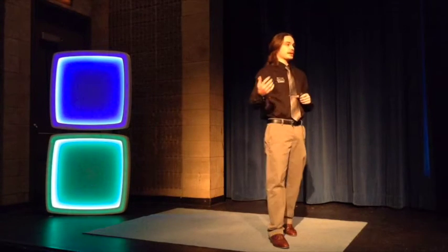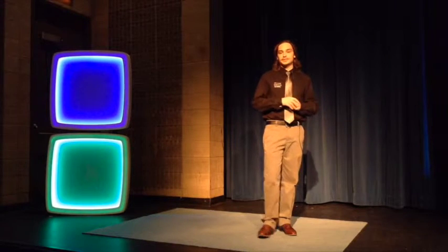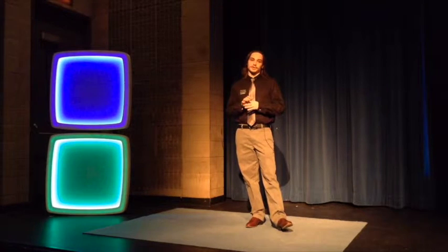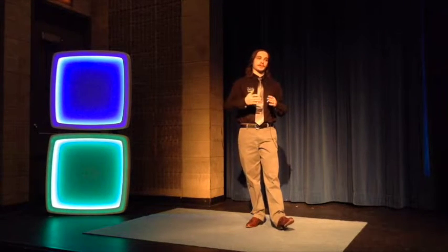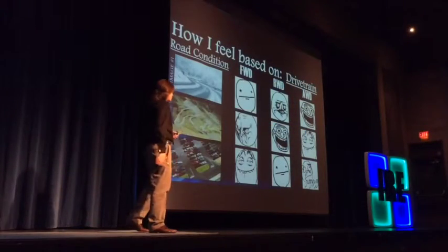Then you'll have rear engine vehicles, which are going to be a highly rear bias weight distribution. And this is considered the least desirable because having more weight in the rear end will allow your car to have momentum to throw that rear end out. But having more momentum will make it harder to recover from a drift.